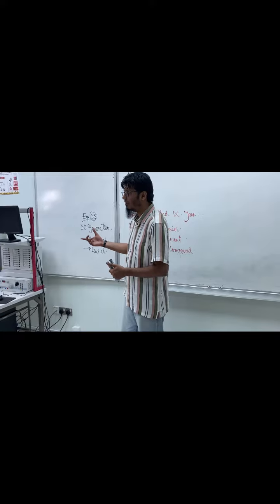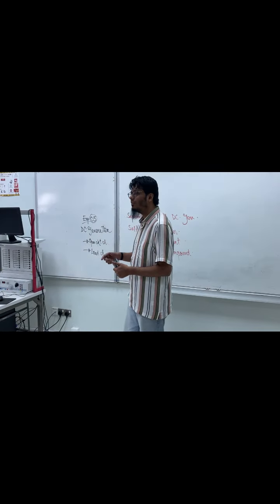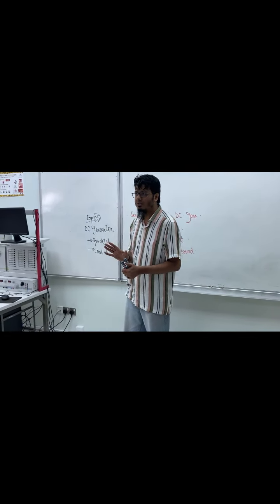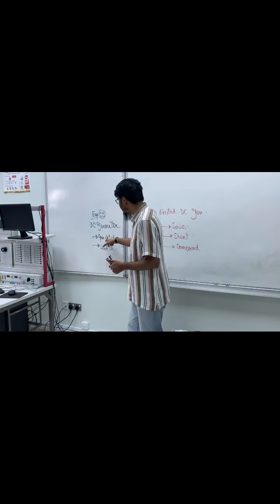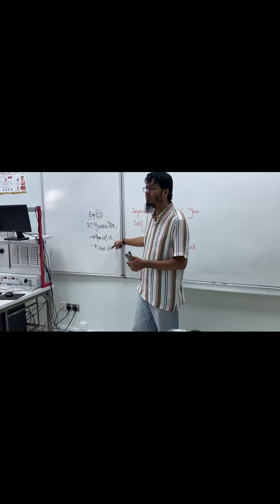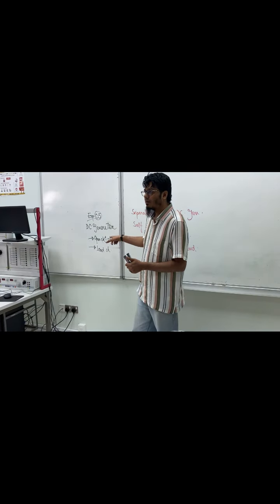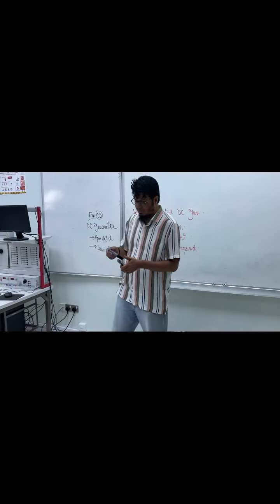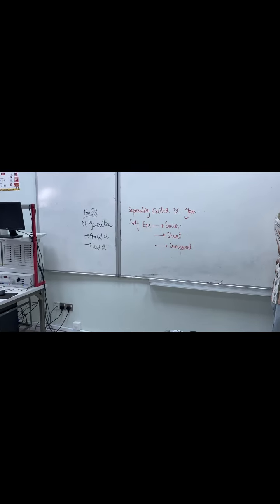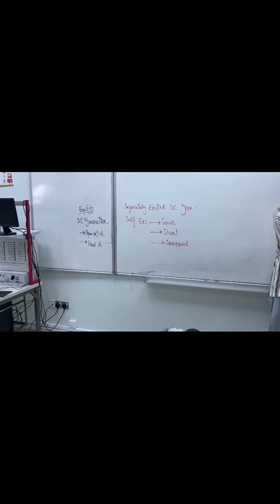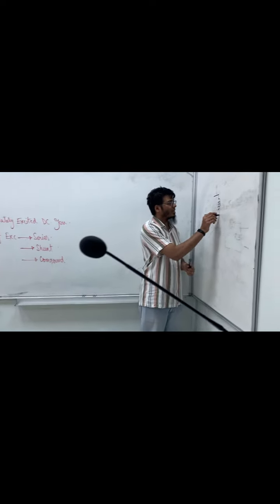Characteristics means behavior. And what are the behavior or the characteristics of a DC generator? We started in the lecture class. One of them is open circuit characteristics. Can you remember open circuit characteristics? If you can remember, in the generator we have a field circuit.